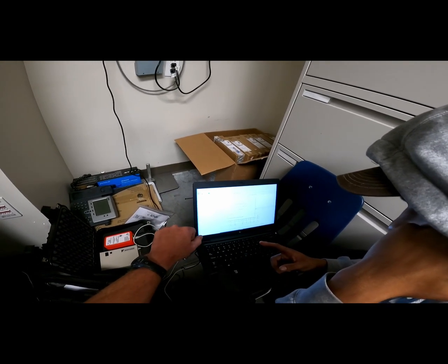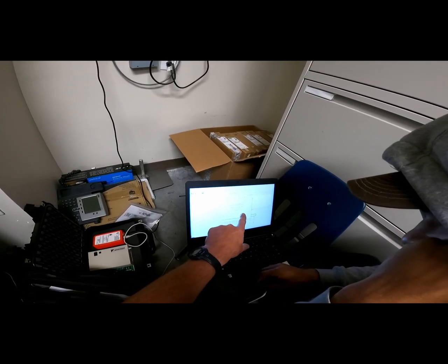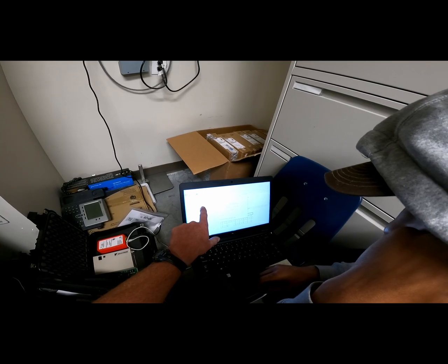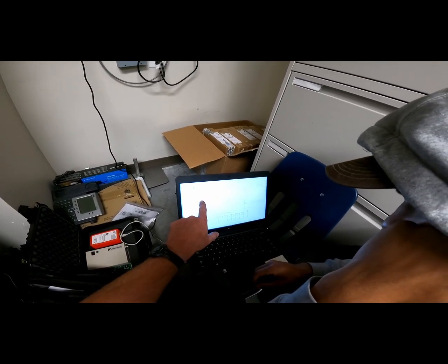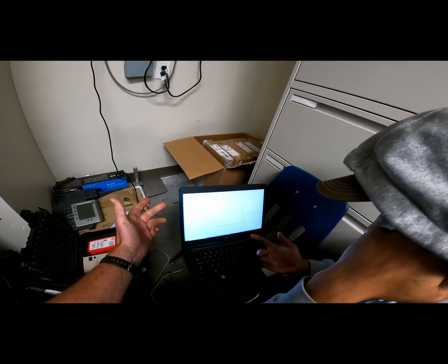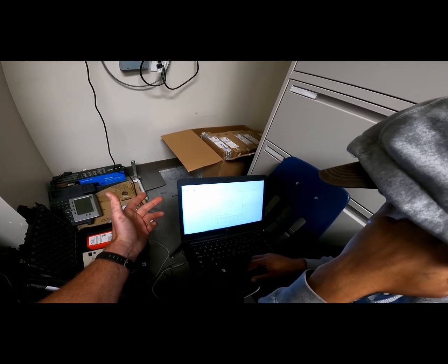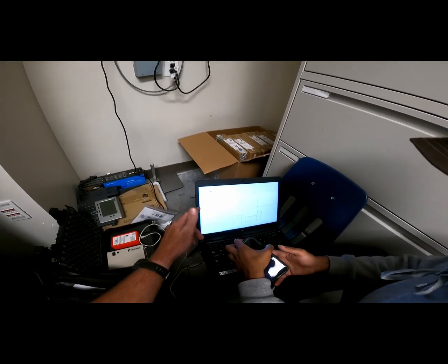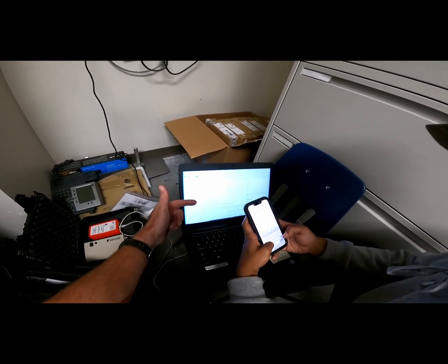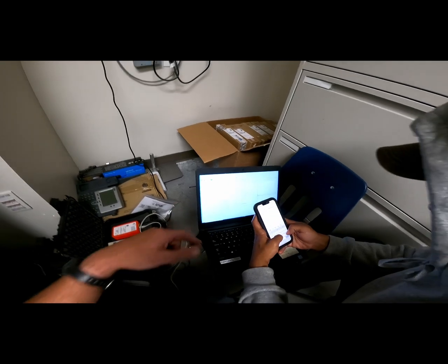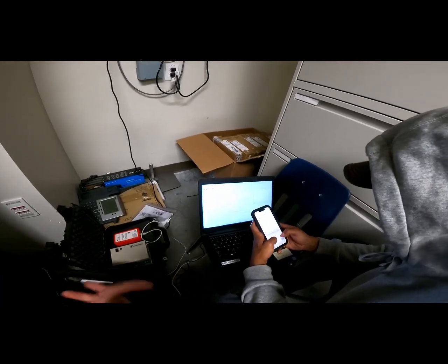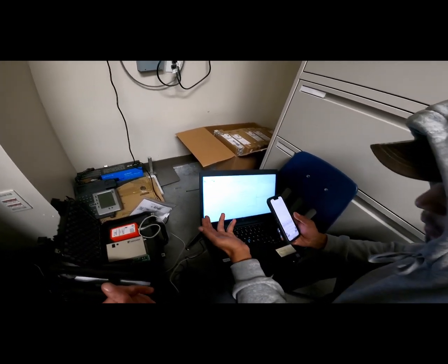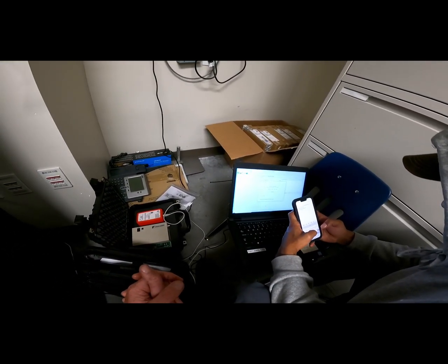So one thing you want to be careful of is that you don't cancel an automatic search, because a lot of times you might get to 54 and then it starts searching real fast because it's not finding anything. You go ahead and cancel it and you don't even know that there's 3 or 4 more outdoor units out there. They always get through. It's time consuming, but I would recommend letting those numbers run all the way out to 250 if you're not sure, because it's all based upon whoever installed it. If they wanted to, they could have made the address of the outdoor unit 212 if they wanted to.